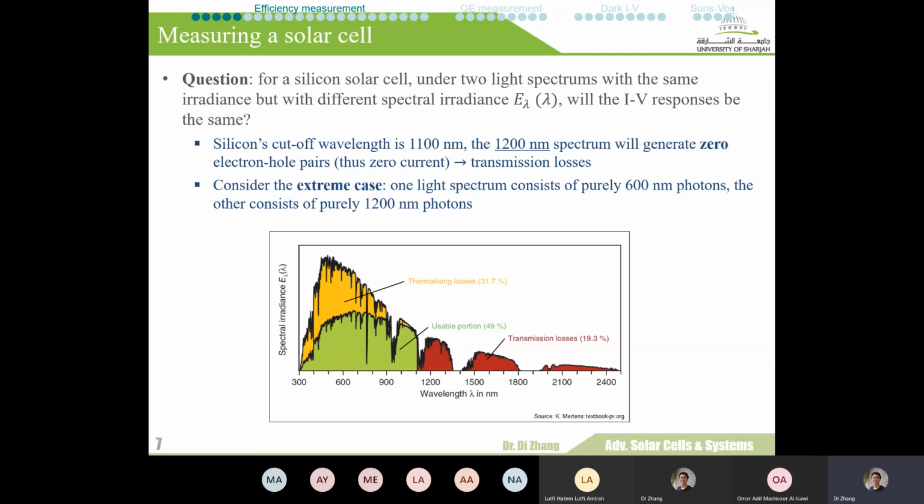So specifically, we were talking about why do we need exactly 1,000 watt per square meter irradiance in STC, and also besides the irradiance requirement, why is it necessary to have the spectrum requirement? Okay, the reason for this is one thing we tried to emphasize last time, that each solar cell will respond to different wavelengths differently.